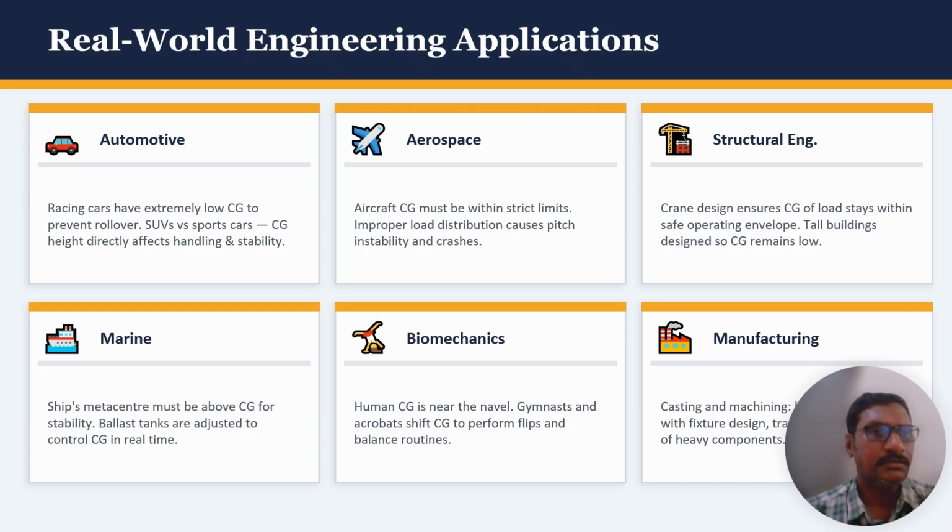And then coming to the second application, aerospace engineering. Every aircraft has a defined center of gravity envelope, a range of allowable center of gravity positions. If the center of gravity is too far forward, the aircraft nose dives and the pilot needs to pull back constantly on the controls. If the center of gravity is too far aft, the aircraft becomes statically unstable.